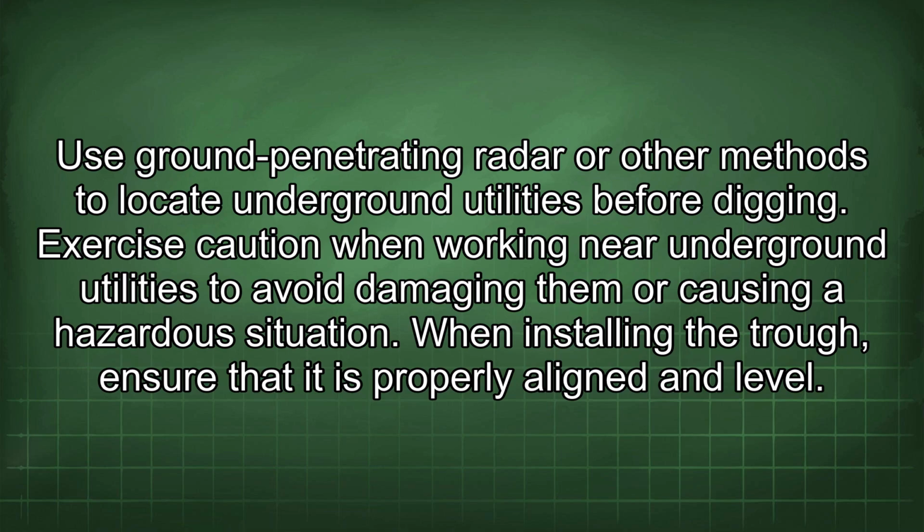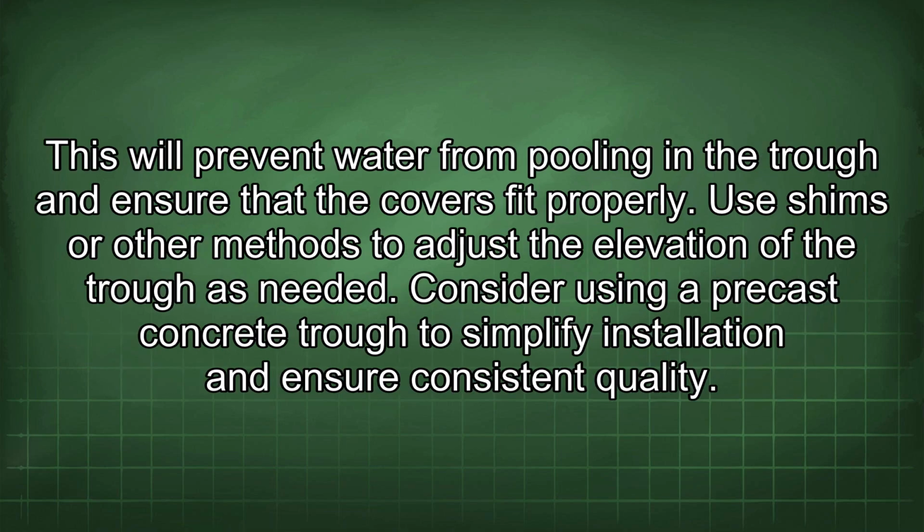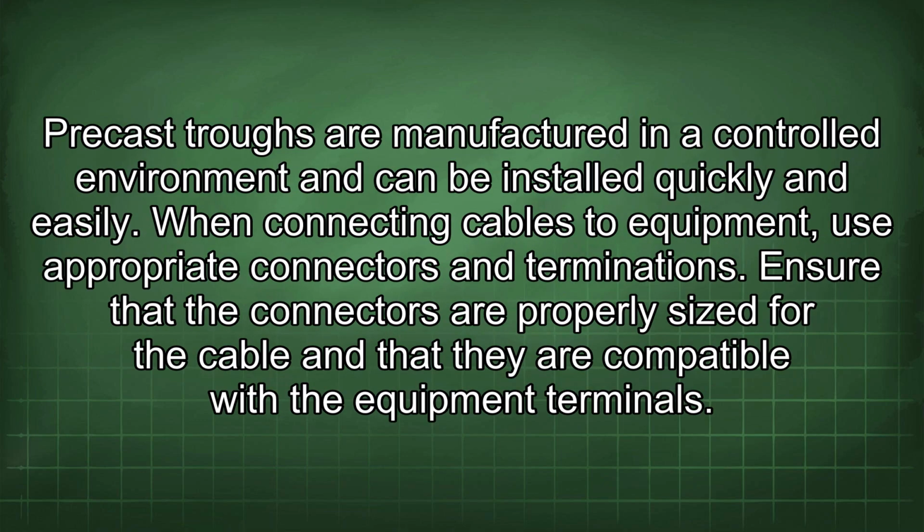When installing the trough, ensure that it is properly aligned and level. This will prevent water from pooling in the trough and ensure that the covers fit properly. Use shims or other methods to adjust the elevation of the trough as needed. Consider using a precast concrete trough to simplify installation and ensure consistent quality. Precast troughs are manufactured in a controlled environment and can be installed quickly and easily.